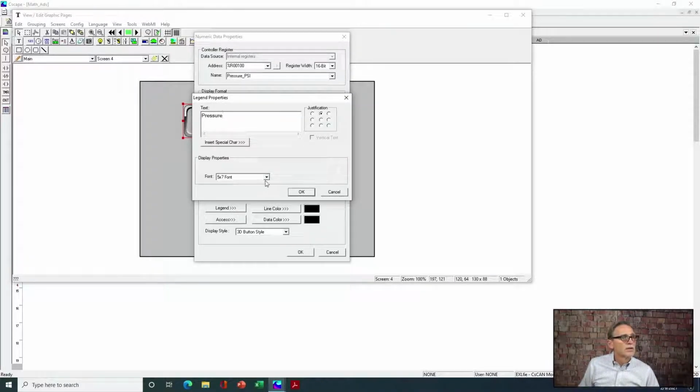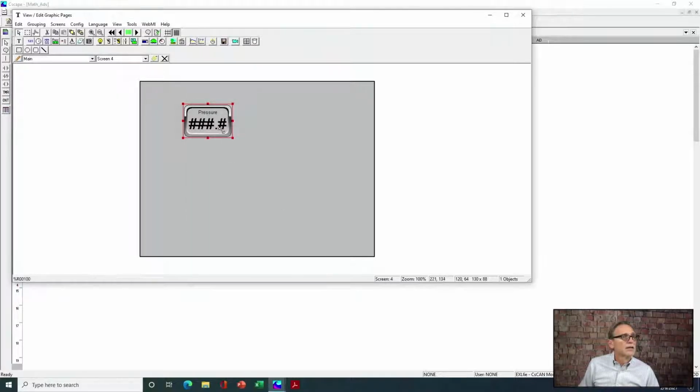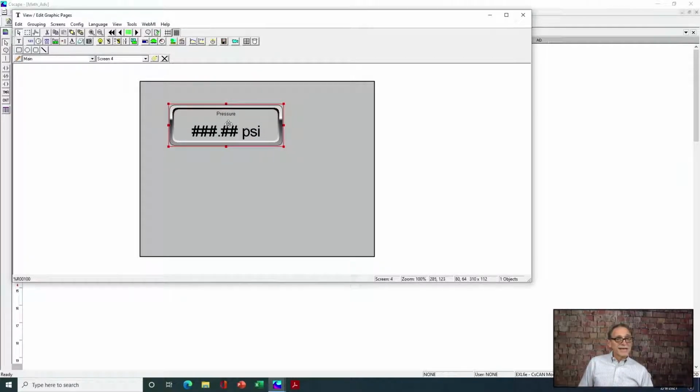Put a little bit of a bigger font size there, and expand it so it isn't too small. There we go. All right, so that gives an example of how all the scaling that we did stayed as integers, yet we're displaying the value on the screen in engineering units, and we never converted from an integer to a real value. Okay, so that's one way to do it. And it doesn't work for everything either, because sometimes you could have potential overflow issues and those sorts of things.